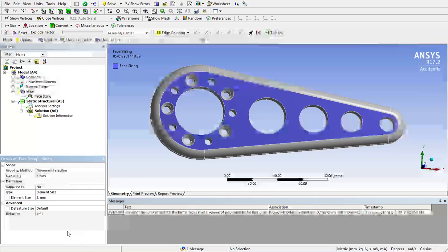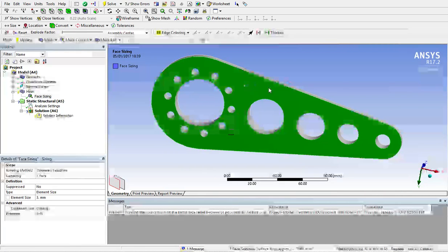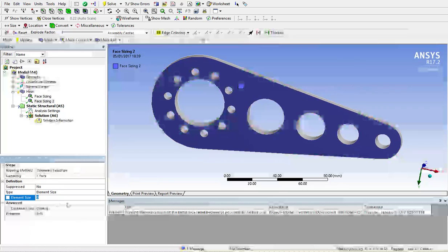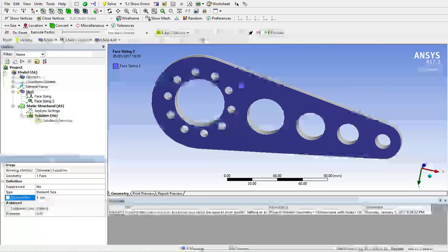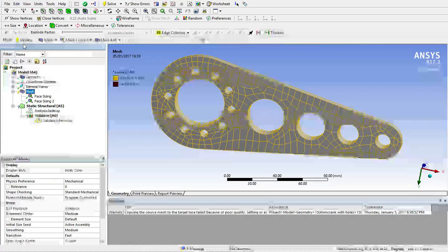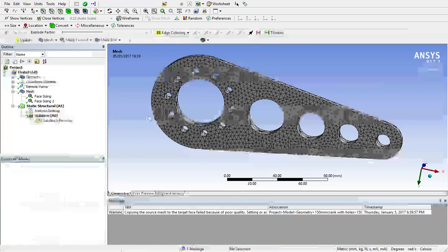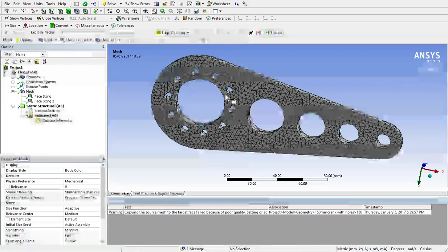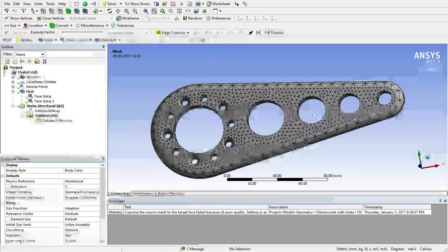Again, this is where you use your initiative, show the things you know about ANSYS, and you can change that to whatever you want. And I'm just going to do the same here. Select, insert sizing on the back face. Again, 3 mil. And then if you click the mesh there, you can click update, the little lightning bolt there, and that will show you the new information. Nice thing about ANSYS is when you have made changes, your menus, rather than the green tick, will have that little lightning bolt and you know you have some stuff to update. So this is looking much better.